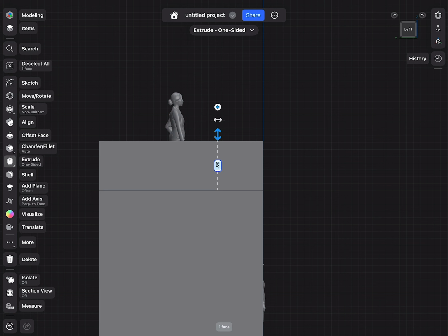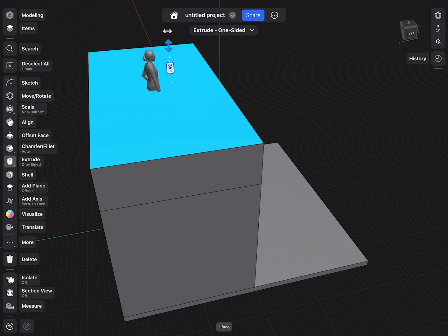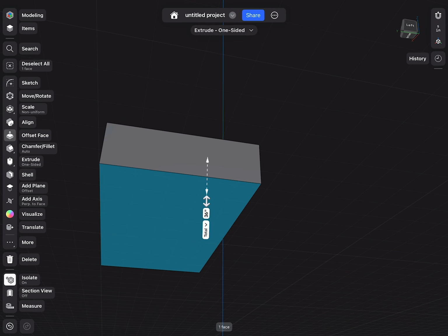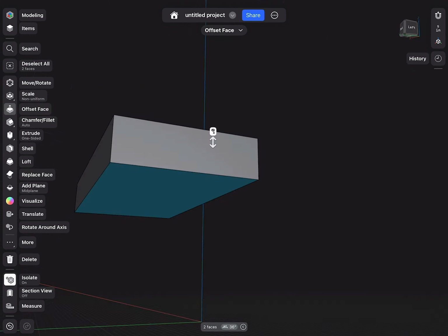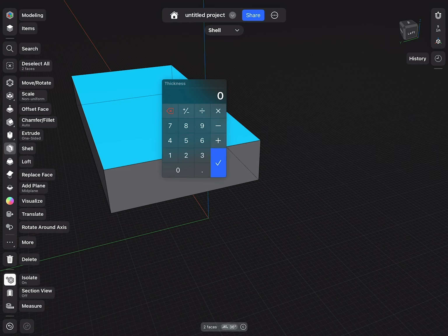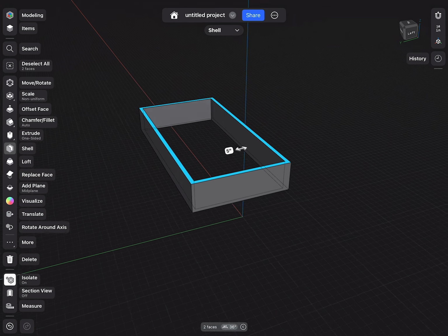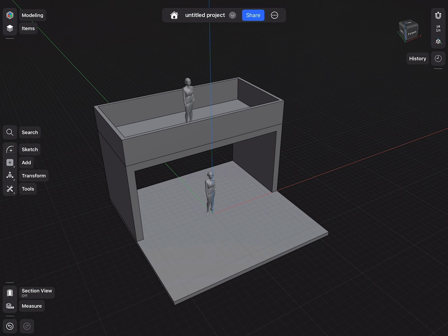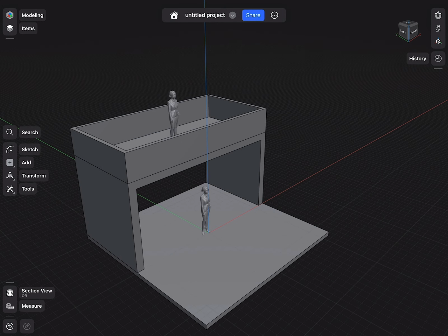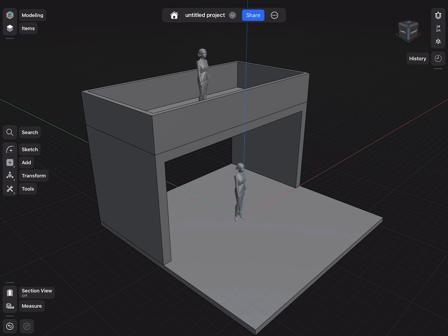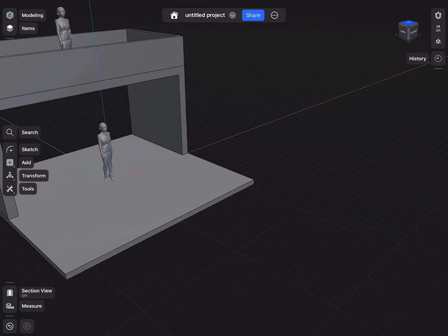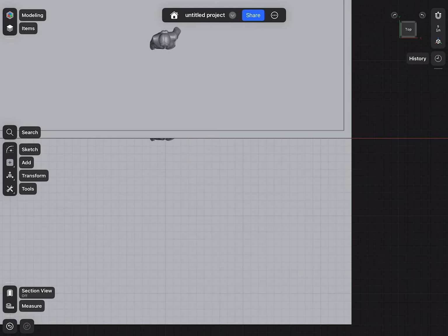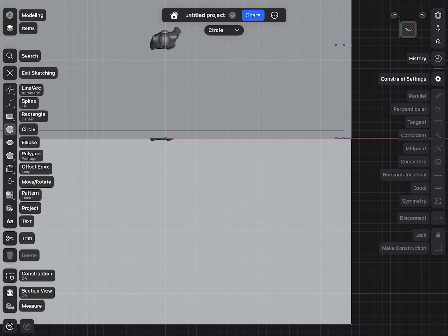Okay. So I'm at 36, so this is actually good. Then these two faces I will select and shell 5 inches for the thickness. Beautiful. Cool, huh? So there we see this. Okay. To create, let's say for the person below, a post, I make a sketch.